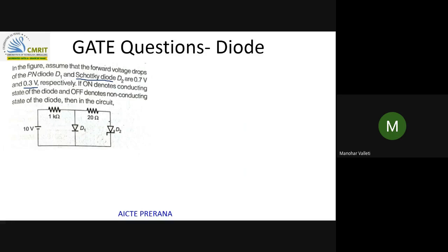And here, always be careful. Till now, if plus is connected to the anode, we are assuming that it is forward bias and doing it. Finally, we are getting the proper answer only. But whenever very little resistance is there in the circuit, be very careful about it. Because across the parallel branches, the same voltage will be there. So let us say, based on this, both diodes D1 and D2 are forward biased, replaced with the cut-in voltage. Let us assume. But this is 0.3 and this resistance is very, very less. And it needs to have 0.7 here. There may be more possibility that you won't get 0.7 here.